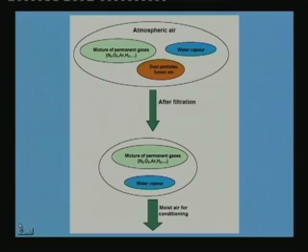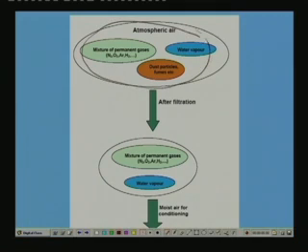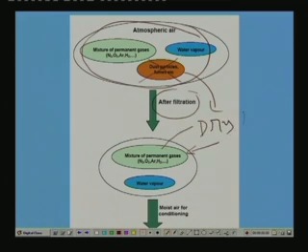So, as I said, this entire thing is your atmospheric air, but in a typical air conditioning plant, what is done is, first of all, we filter this air. Okay, when you are filtering this air, you remove the dust particles, fumes, etc. Once you remove them, you are left with a mixture of permanent gases, and you call this portion dry air, plus water vapor. So, this is what is actually processed or conditioned in an air conditioning plant. This mixture of dry air plus water vapor is sent to an air conditioning plant for conditioning. So, this mixture is called moist air.